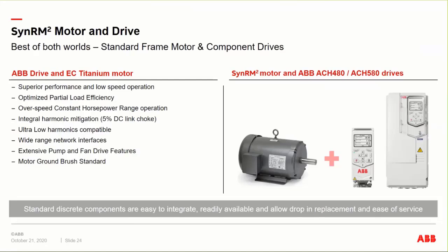If you really want to step up and get rid of the harmonics, there's the ultra low harmonic capability. So if harmonics are a concern, we think this is a better solution as well. Because it is on a drive, we also put a standard ground brush in these to get rid of bearing currents and common mode voltage. We can do ceramic bearings and things like that as well.